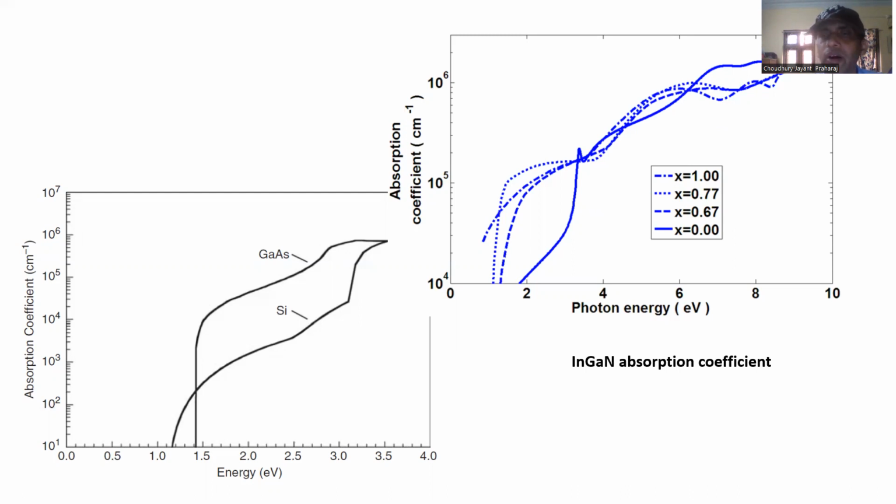A little bit about three different kinds of holes. So we have the so-called heavy holes, the light holes, and then there is the spin-orbit split-off holes in these materials. And now the spin-orbit split-off hole has a valence band maximum, which is slightly below the valence band maximum for heavy holes and light holes. Now the heavy holes have large effective masses, the light holes slightly smaller, and the split-off holes tend to have even slightly smaller, and they're different effective masses.